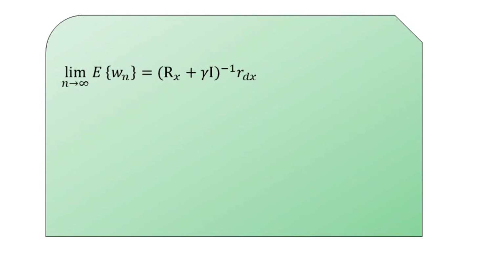For minimization of the error, the leaky LMS algorithm may also be derived using the LMS gradient descent algorithm. Here we minimize the error zeta of n, which equals the magnitude squared of e of n plus gamma, the leakage coefficient, multiplied by the squared norm of w_n.